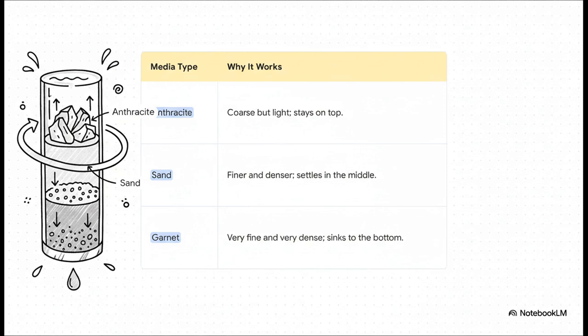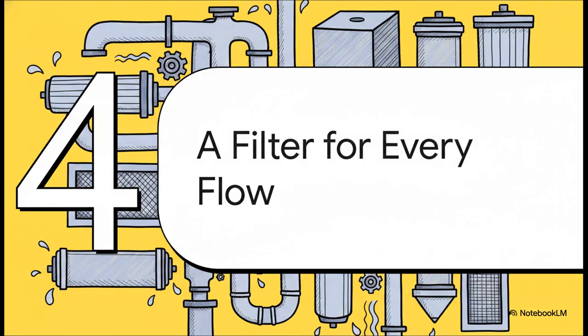The secret is density. The lightweight anthracite naturally wants to stay on top, the heavier sand settles into the middle, and that super dense garnet always sinks right to the bottom. So after every single cleaning cycle, the layers perfectly reset themselves. It's just brilliant.